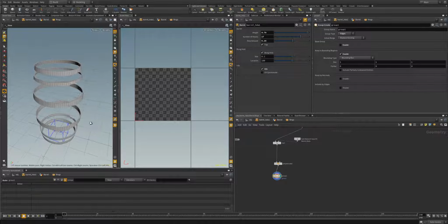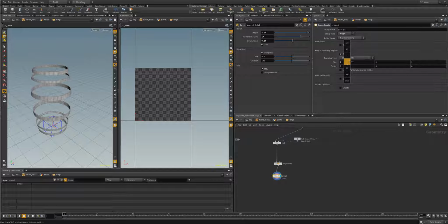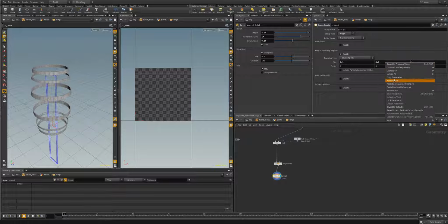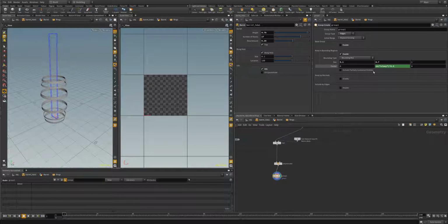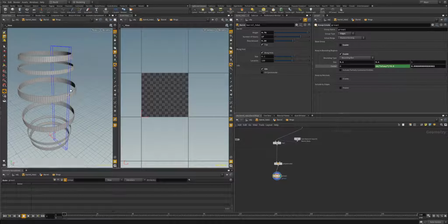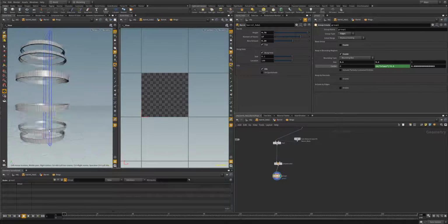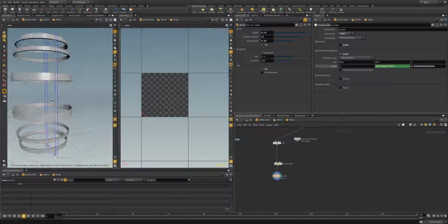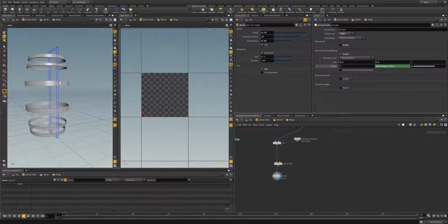And we could try to resize this, maybe make it thin, and we could do the bounding box of this and try to size it appropriately with our barrel, maybe move the offset here so that we're always selecting this one set of edges right here, and then UV flatten that.